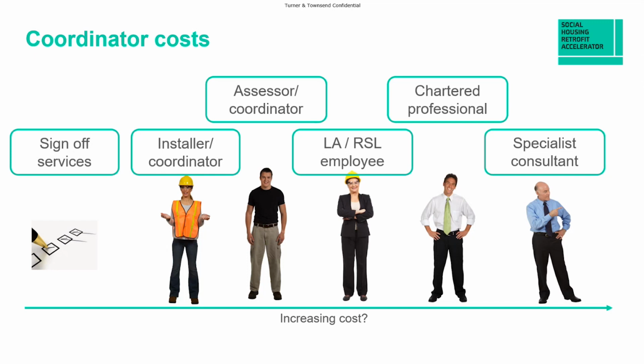In terms of EWI installation, which was always quite an interesting one, there were 3 stages of inspection previously under various funding regimes, and I would say they're quite good stages to have. That would be when you put the insulation on, then when they put the base coat on, and then a final inspection when all the works were complete. They are quite good points to do that inspection, and anybody that's worked as a retrofit coordinator for a while will understand in the business what those inspection points would be.